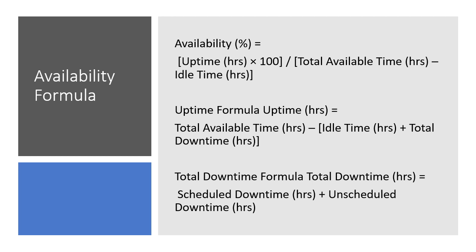So the idle time is not a problem of the maintenance department. It is basically the time when the machine is not allowed to operate. What the maintenance department is concerned about is total downtime, that is scheduled downtime plus unscheduled downtime. Scheduled downtime is when you do the scheduled maintenance and unscheduled downtime is when you do the corrective maintenance.